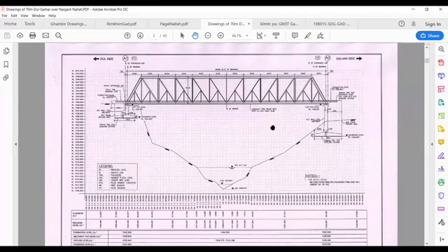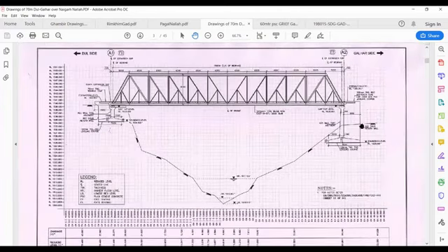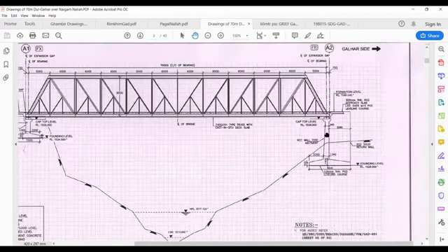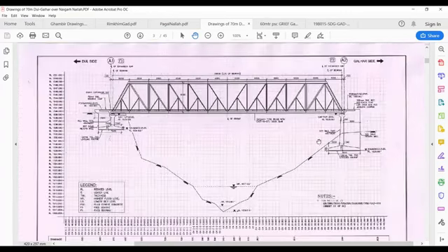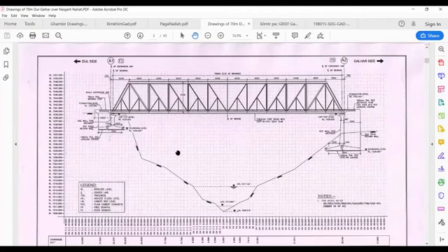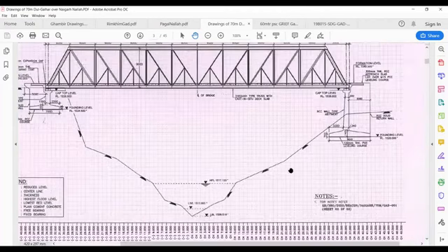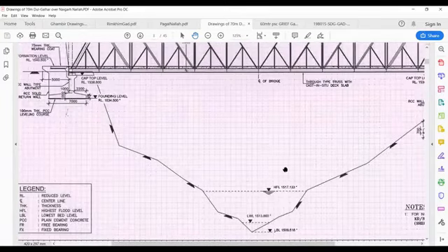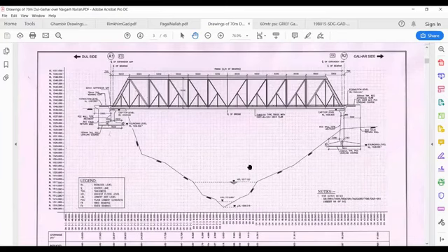And the second consideration is what level of the bridge they want to achieve. Usually a road is coming from behind, so if the road is coming at this level, we cannot build the bridge higher. And third, if the level of the road behind is not an issue, then in this case they could have constructed the bridge at this level as well. If they were building the bridge at this level, the span would have been 35 or 40 meters instead of 70. It would have been okay. But specifically in this case, their road level is somewhere here, so they have to make it like this.